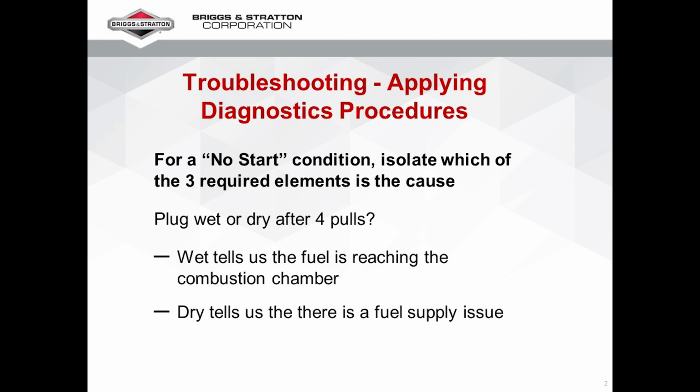Attempt to start the engine, pull start it at least 4 times or crank it for at least 10 seconds if it's electric start. From there, remove a spark plug and note whether the electrode end is wet with fuel or if it's dry. This will give us instant direction where we need to go next.